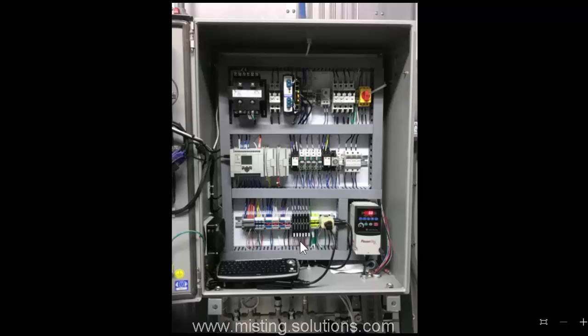We'll call it a read time delay, that at a certain point the controls will react to that read. And typically that read signal is every 30 seconds. It is adjustable, and we'll see that here in a minute, but 30 seconds is the typical setting. In other words, every 30 seconds, the microcontroller looks at the DC signal, 0 to 10 volts coming into it, and says, oh, I've got to increase my output capacity, or I've got to decrease my output capacity.